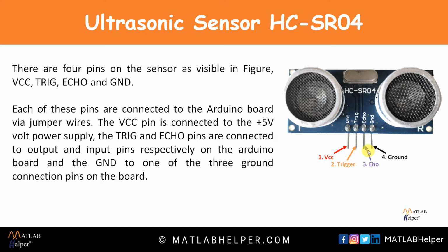So the advantages of using this ultrasonic sensor HCSR04 are that it is low cost and it can provide an effective distance to obstacles ranging from 4 cm to 4 meters, and it also produces a traceable amount of data for interpretation.